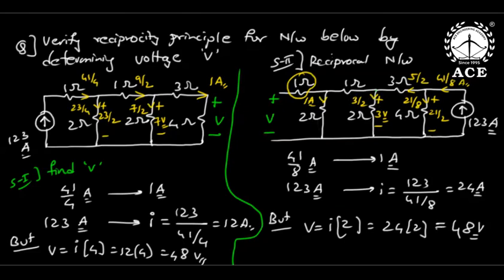See, this is 1 volt plus 2 volts. This branch and this branch now are parallel actually. So this is 3 volts. So here also 3 volts will come. Now 3 by 2, current is how much? Voltage by resistance, 3 by 2. So now again KCL here. 3 by 2 plus 1 is 5 by 2 ampere.